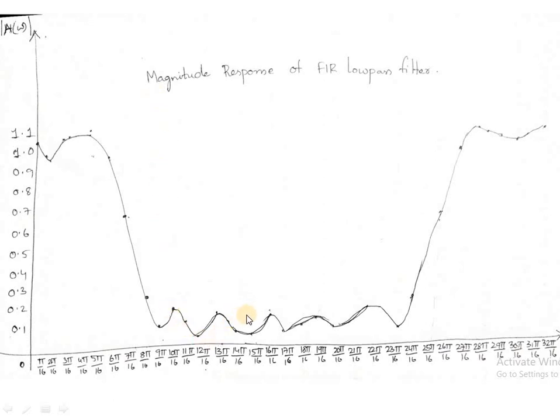Here I am able to observe that the passband has slight fluctuations. We are able to see that it is having some ripples in the passband, both the passbands, and also I am able to see that there was a transition band from passband to stopband, where slowly it has been decreased, and similarly it also has been increased slowly to those ideal conditions, and we are also able to see some ripples in the stopband based upon all those values.